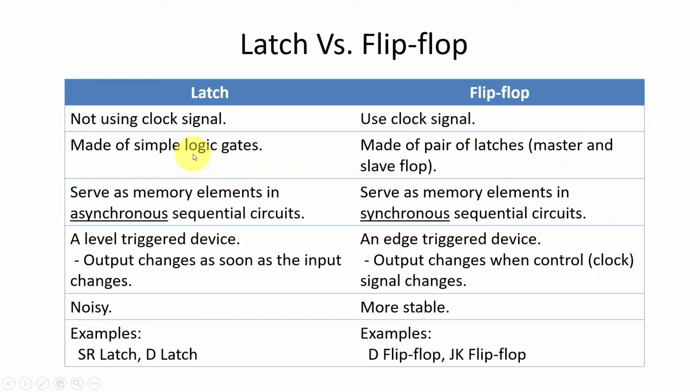And also the latches are made of simple logic gates. Flip-flops are again made of logic gates, but they contain latches internally as well. Of course, the latches are again logic gates. So therefore, flip-flops are more complex logic circuit components. And both can serve as memory cells. But when it comes to latches, we use latches as a memory cell in asynchronous circuits. Asynchronous means the timing is not important. Whereas we use flip-flops as memory cells in synchronous sequential circuits. So there are situations where a latch is good enough, and there are situations where the flip-flop is needed.